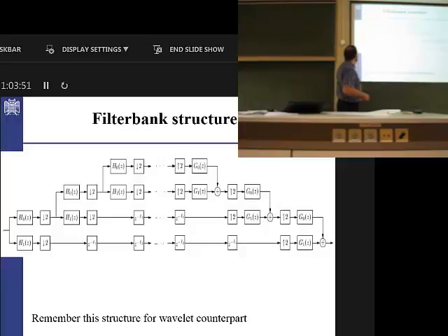In the beginning, what you try to do is to take the lower frequency and the high frequency part, factorized or separated, and then again for the lower frequency you can have finer resolution. So this is the coarser resolution. This is actually the details of the signal, the high frequency part of the signal. But the lower frequency part is also again possible to divide into finer resolutions.